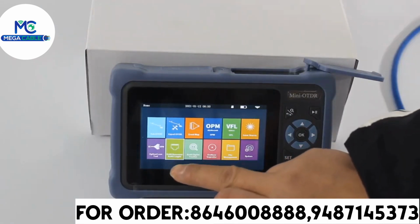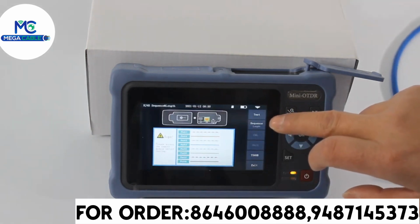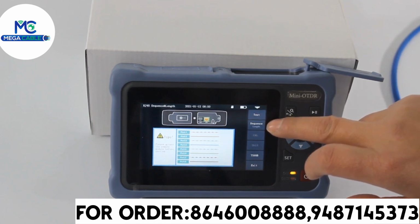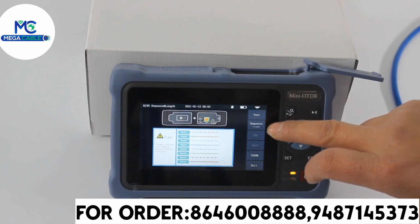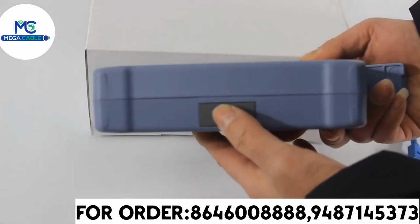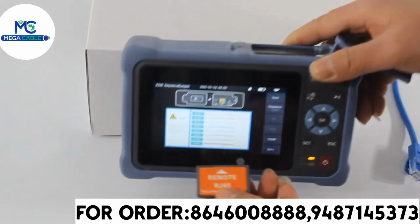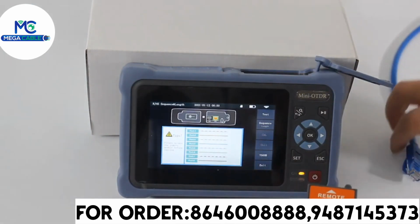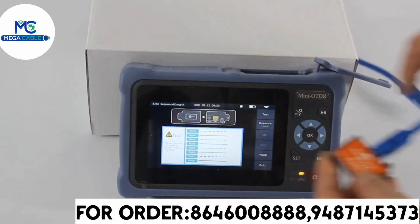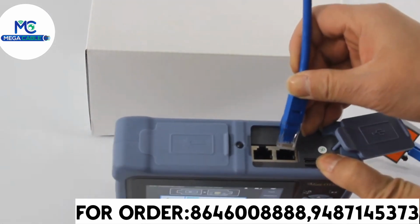Click RJ45 sequence, RJ45 lens. When we see sequence is in white color, it means we can test the sequence of RJ45 Ethernet cable. On the bottom of OTDR, push the remote module inside, and we can take out the remote module. Connect Ethernet cable with remote module, and the other side with Ethernet port of LAN 2.